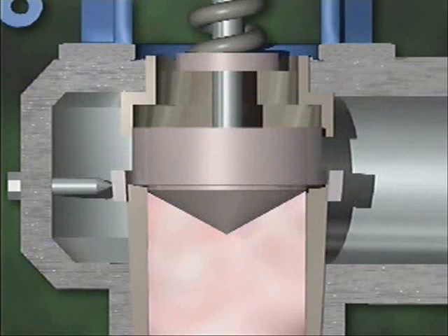When the system pressure drops to a predetermined value below the valve's popping pressure, the disc drops down on the seat, closing the valve. This predetermined value is the valve's reseating pressure. Typically, as the force of the escaping steam is lost, the valve shuts suddenly. A small cushion of steam trapped in the huddling chamber keeps the disc and the seat from slamming together hard enough to be damaged as the valve snaps shut.